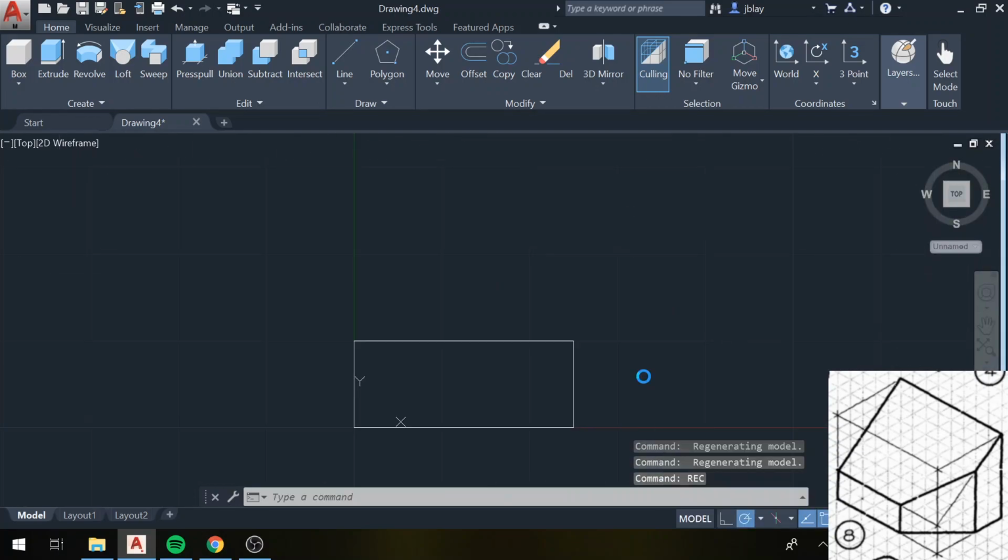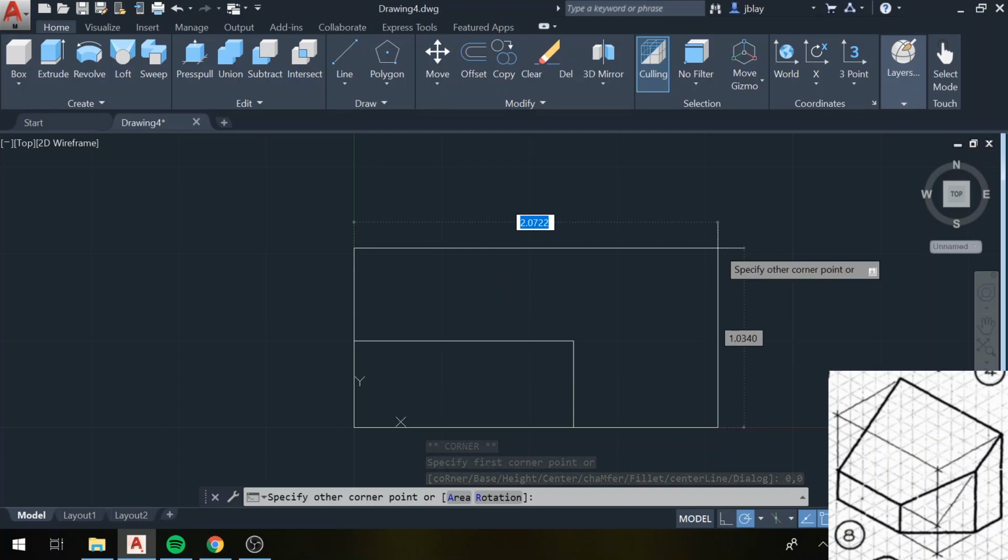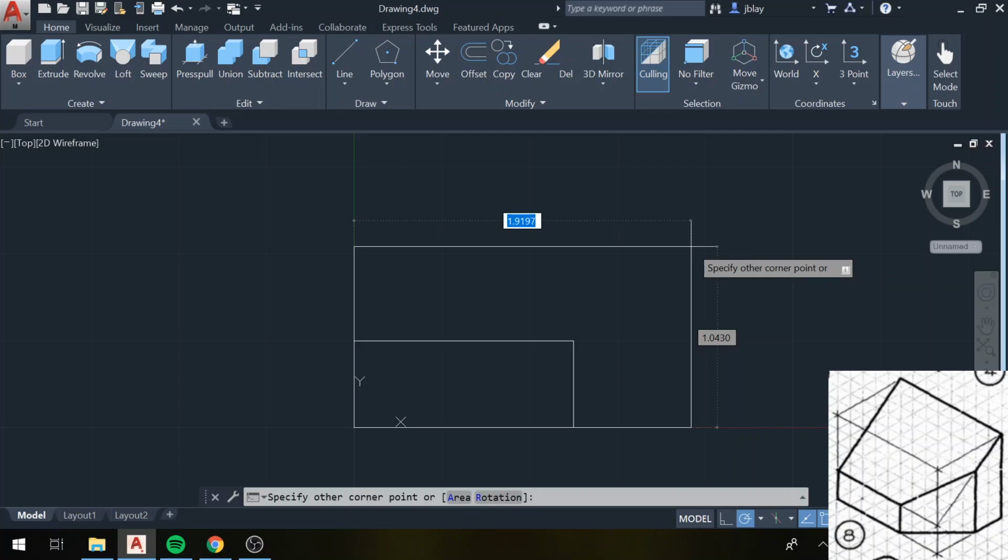I'm again going to draw a rectangle. I snapped the top view so I can see that these things line up properly. 0, 0, because I want that bottom left corner to be in the same spot. And then my width is going to be the same as the overall width of the shape, because this cuts all the way to the end width-wise. 1, 2, 3, 4, 5, 6, 7, 8 units, which is going to be 2 inches.